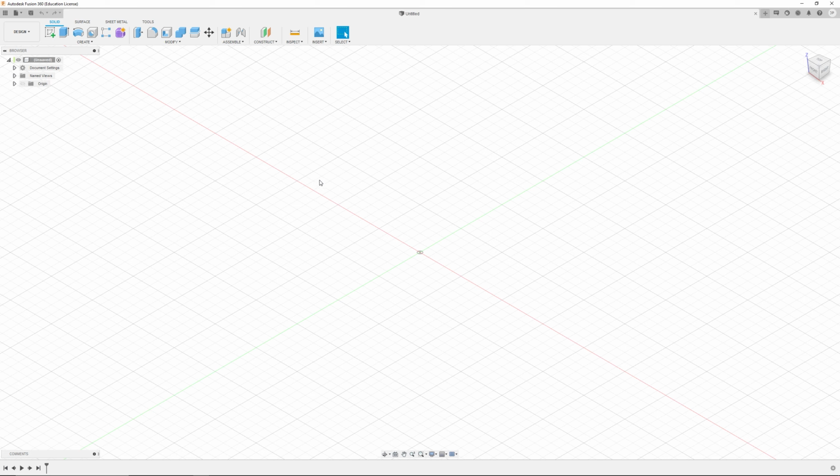So the first step in creating an assembly is to right-click your part and do a new component. This little box will pop up asking you what kind of type, internal or external. We want this to be internal because we want it to all stay within the same document. And then when I hit OK, you'll notice that this shape changes to essentially two blocks on top of each other next to another one. This implies that this is now an assembly.